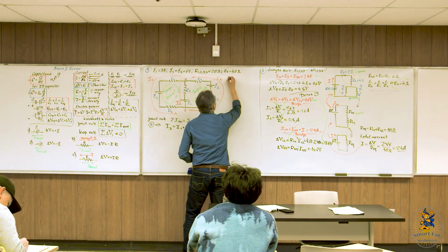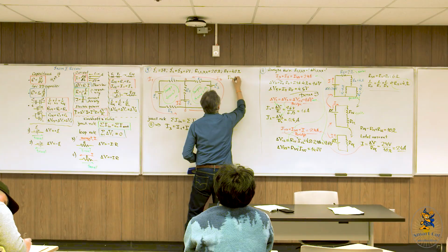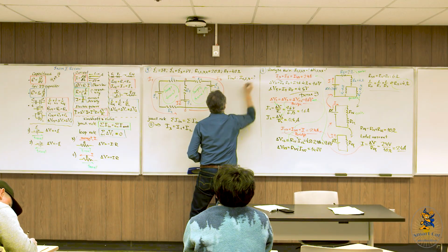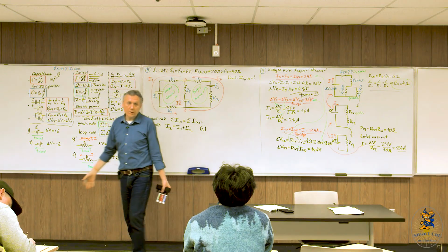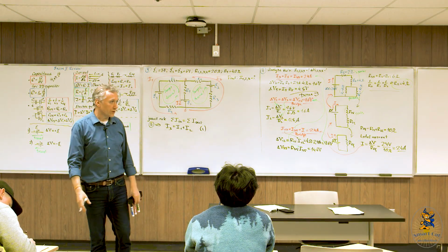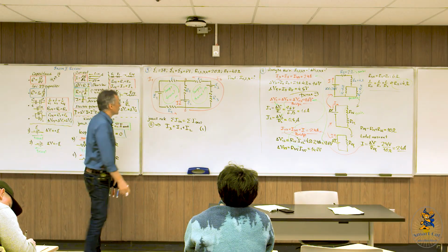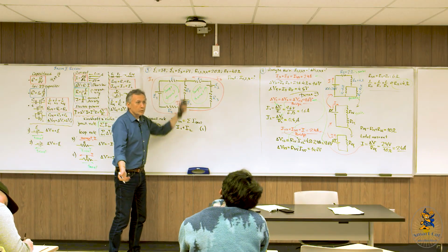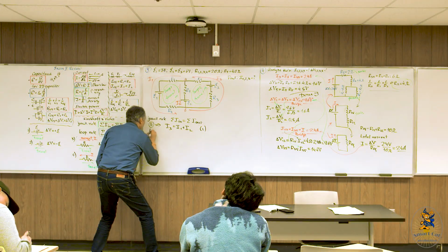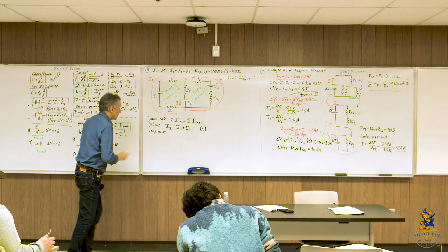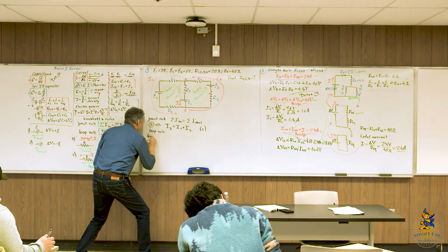All right. So we still need to get two equations because overall we have three unknowns. Let me write that down. We need to find essentially I1, I2, and I3. Three currents, three unknowns, so there must be three algebraic equations. One we have, so now we need two. We need to write two equations: loop 1 and loop 2. So now the loop rule. Loop 1.